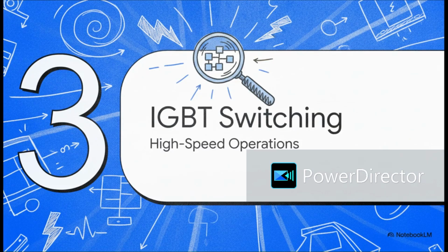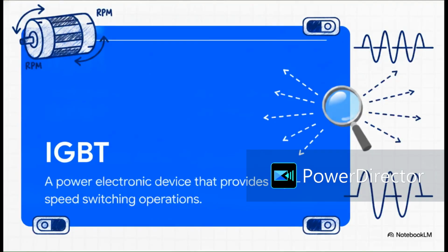Enter the IGBT. The secret sauce here is sheer speed. The IGBT, which, by the way, stands for Insulated Gate Bipolar Transistor, is a power electronic device sitting right there in the inverter section. And its primary job? High-speed switching. And when I say high speed, I mean it is literally executing thousands of on and off operations every single second. It's this rapid-fire switching that sculpts the exact voltage and frequency being sent to the motor.